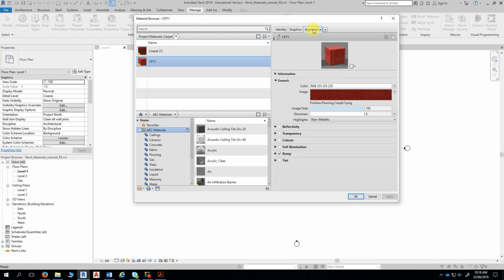So it's a two-step process. It's a common mistake that people make, that they duplicate the material, but they make changes to the appearance asset and then affect the source material, the other material that's sharing it. I said last week that the hand indicates that the asset is being shared. If there is a 0 above the hand, it means that the asset is unique. It's not being shared. It's all coming back?